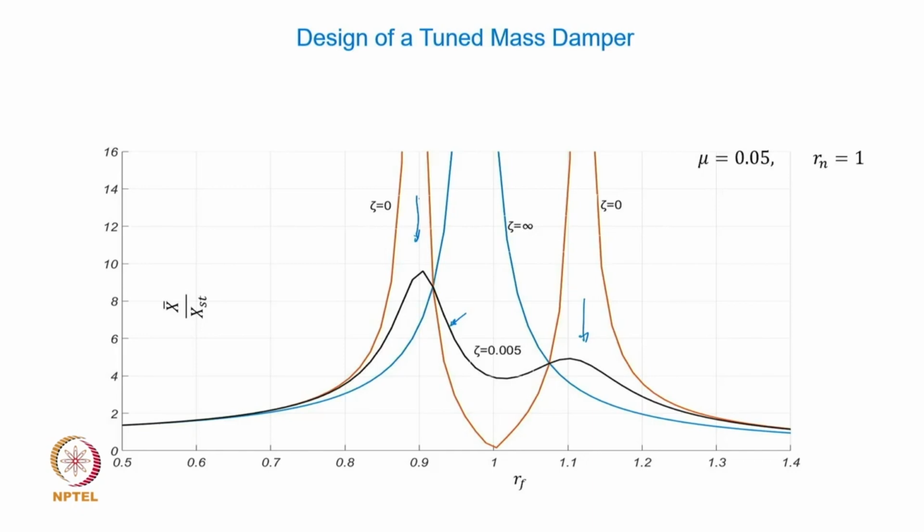Now the problem is we have talked so much about using this vibration absorber for reducing vibrations of the parent system to 0. This was the ideal situation, but that ideal situation created a problem for us: there are two new resonances, and any deviation from this operating condition would take us closer to the large amplitude cases, and therefore we introduce a damping.